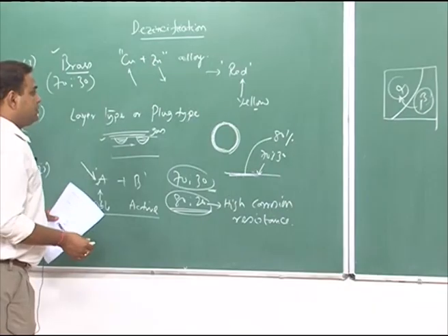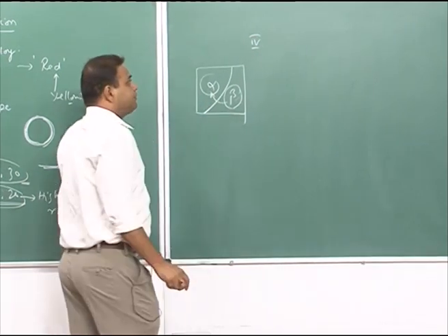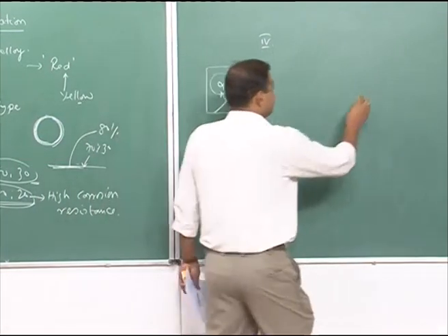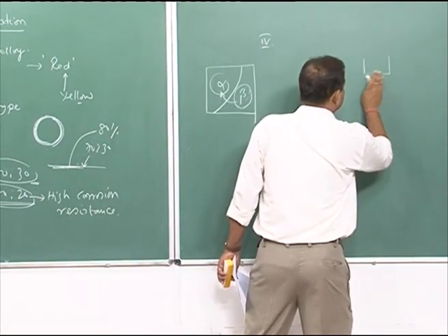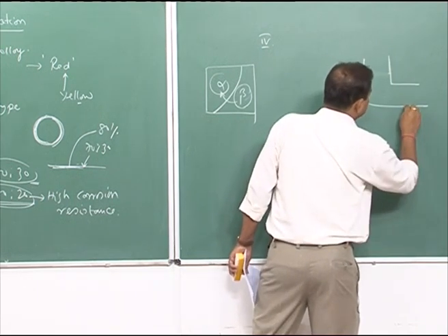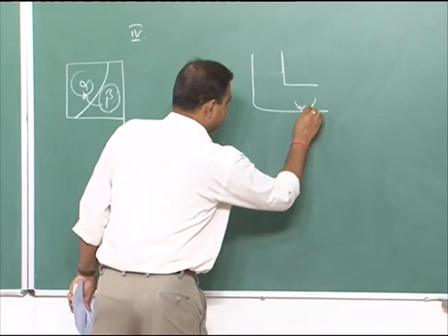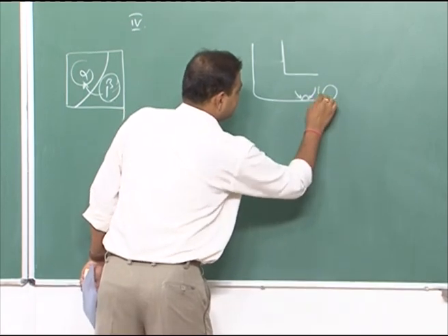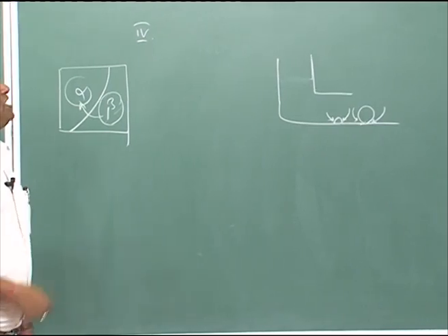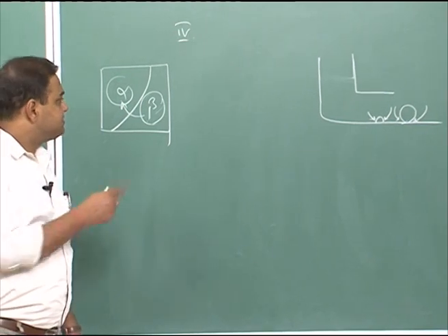Now, the fourth characteristic is whenever you have a conducive condition, let us say crevice formation. Let us say a pipeline, and in that pipeline you have some dirt particle. So then you have crevice formation, like this dirt formation, there is a crevice. Whenever a crevice forms, initially the corrosion starts with the crevice, and once the crevice happens, then the dezincification goes on.